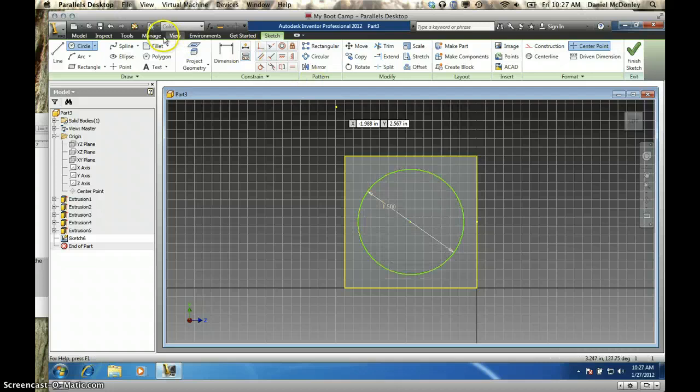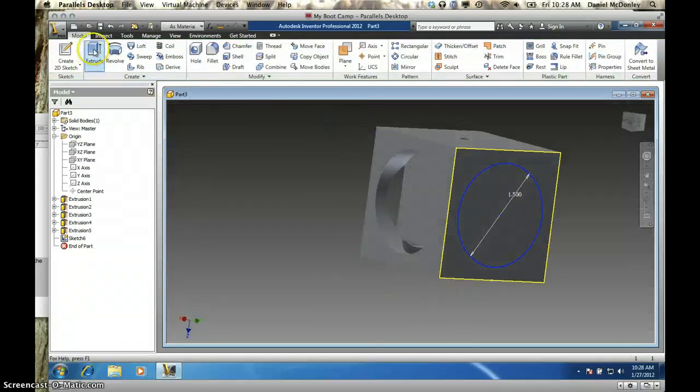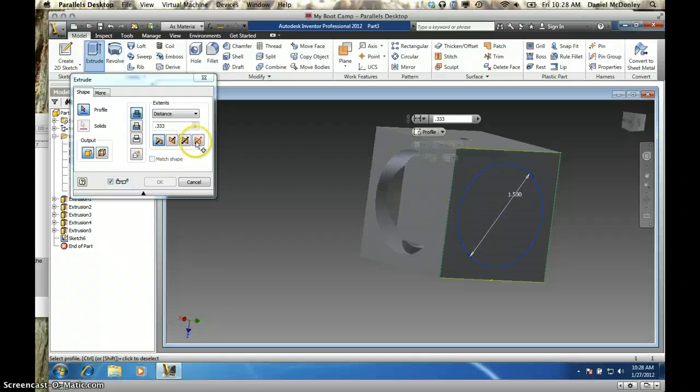You're going to do it over and over and over, and your milling experience is going to be somewhat similar. Take your time with each one because it really does matter that you get everything nice and straight. But this is a good project because you're going to have to find the Z origin for each face as you reset it in the mill. Learning how to create a perfect cube is such a powerful thing.